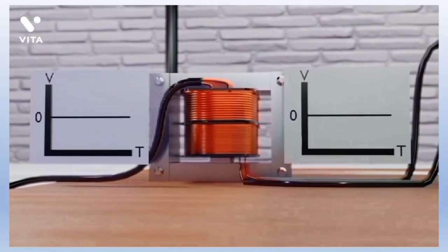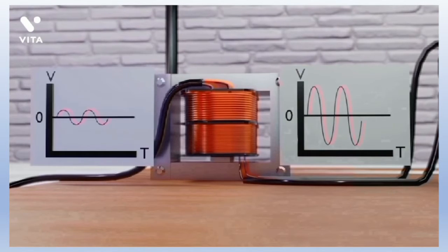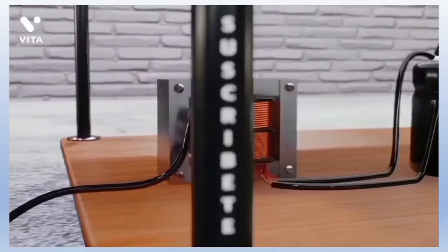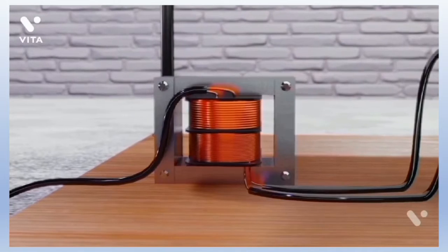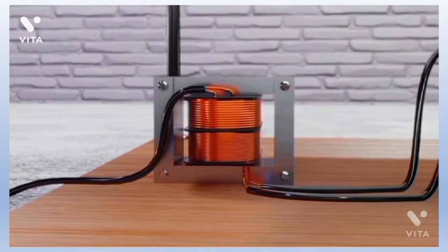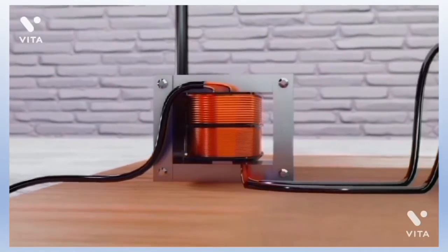That is, if an alternating current wave enters by the primary coil, the wave that will come out of the secondary coil will have the same shape, but with a different voltage, given a high magnetic coupling between the two coils. With this, we will obtain an alternating current with higher voltage, but whose frequency is equal to that of the initial source, say 50 or 60 Hz.